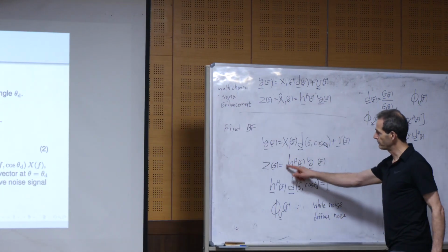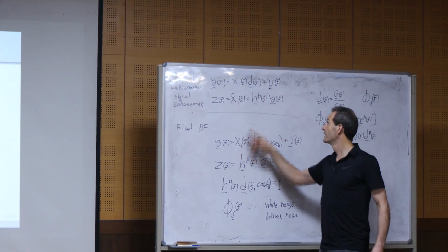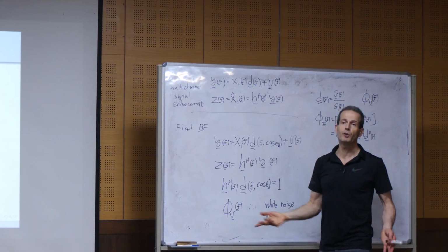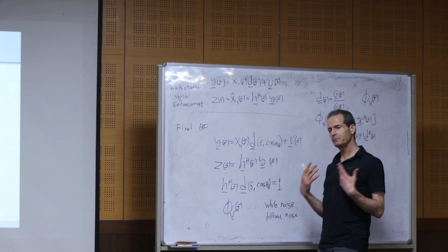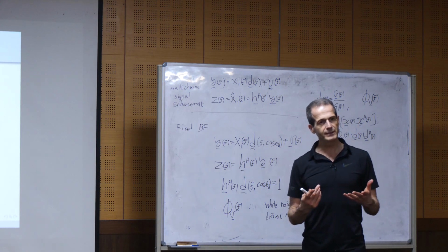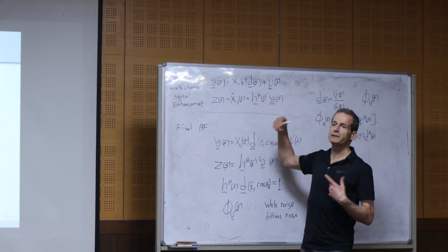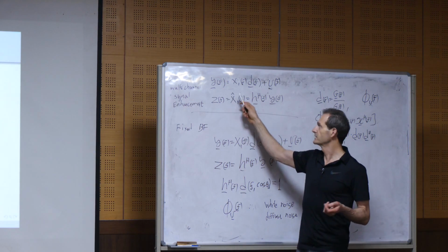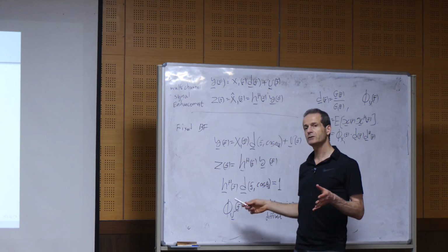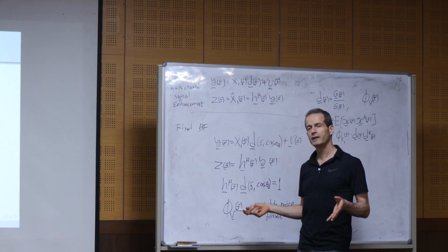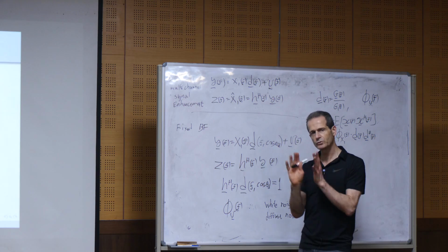So even here, when we apply the beamformer, instead of filter, with signal enhancement we call it a filter, here we call it a beamformer. It's just a name, but when people say beamformer instead of filter, it means something. Filter means that we know information about the statistics of the signals, the desired and the noise. Beamformer means that we don't make assumptions about the environment. If we make assumptions about the environment, we will talk about the adaptive beamformer. We will move on, but first, I want you to understand.